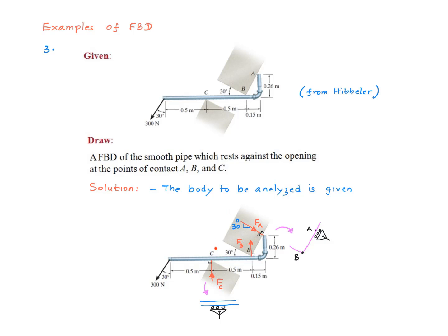As part of marking all the geometrical details, you also want to mark the direction of that force. You might say, well, I'll try to figure it out when I do the problem. Well, that's not good enough. Defining the direction is part of developing the free body diagram, not part of doing the problem. So direction is pretty straightforward. This line makes an angle of 30 degrees, and this force is parallel to that line, and therefore this force also makes an angle of 30 degrees to horizontal.